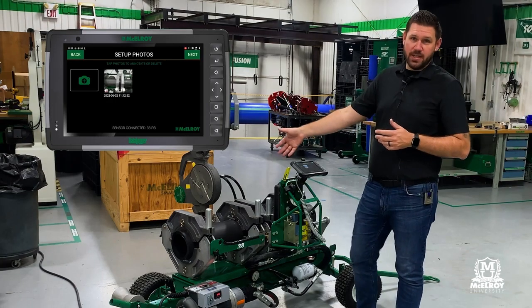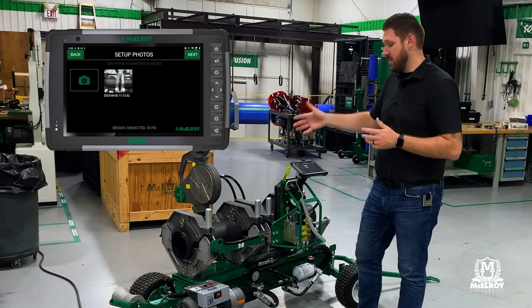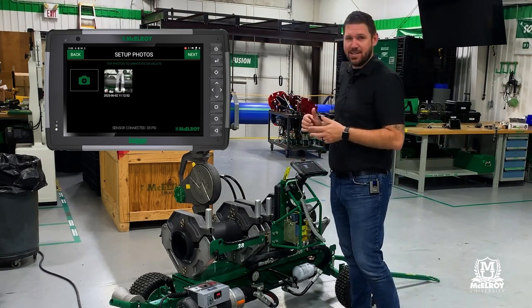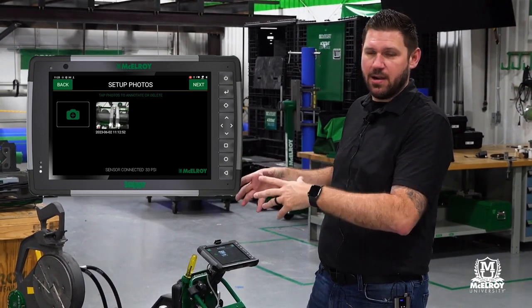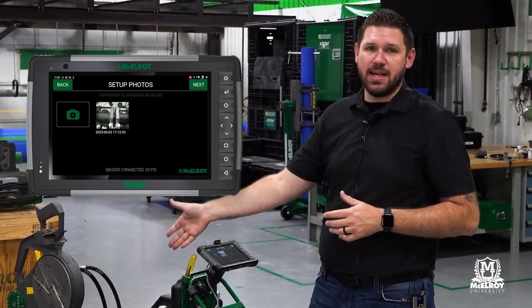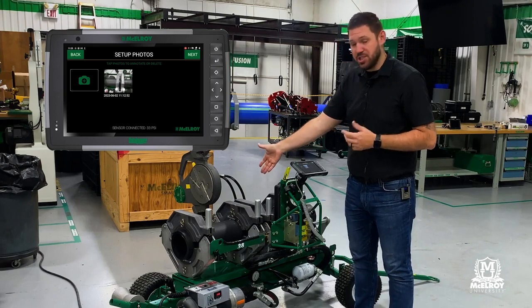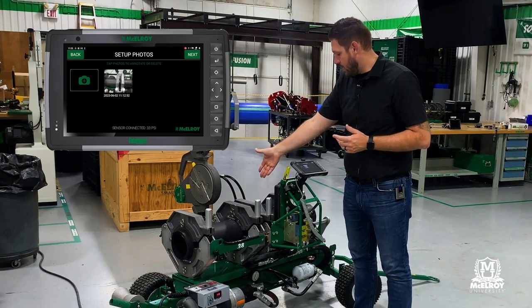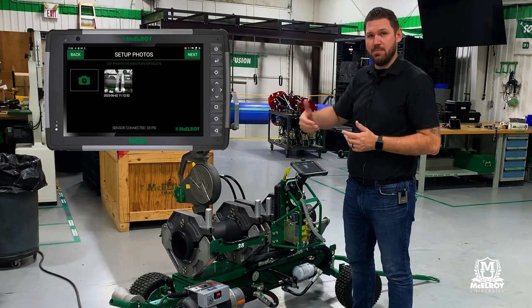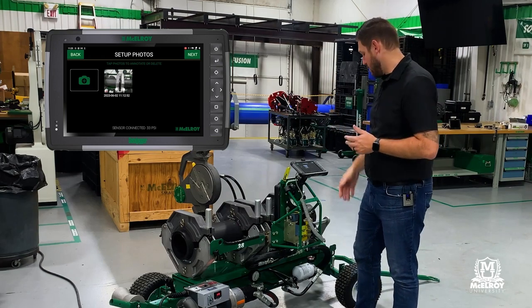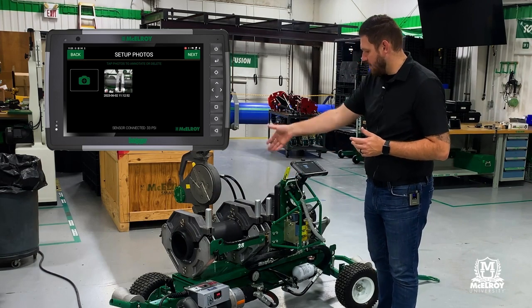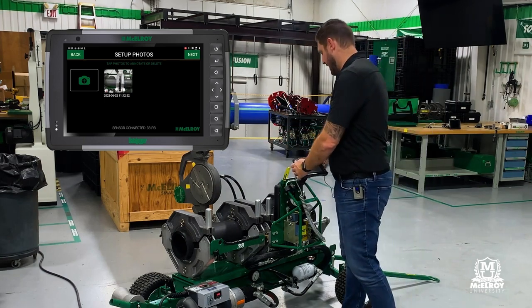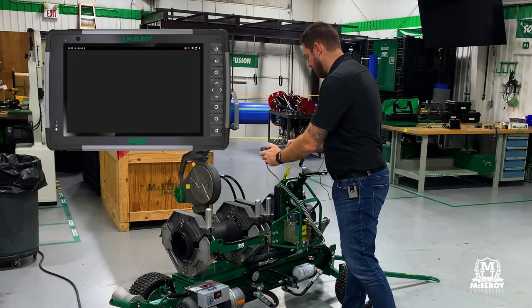And this is where we would want to document what our setup is. This is really when we're turning our attention back to the data logger. We've done all our work with the setting up the pipe, getting our alignment. Now we want to document that. And what I want to do is I want to show exactly what's going on here. And I want to show that I have good alignment, my high-low, I have no gaps. So I'm going to put this down into facing mode. I don't have any gaps, I have good alignment. I can grab my data logger, and I'm going to take a photo of that.